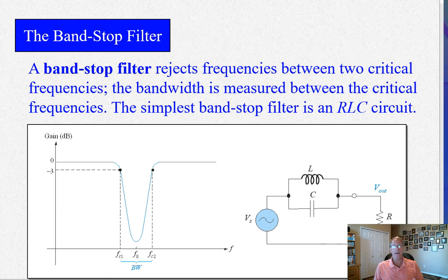And again, you can do that analysis on any circuit that has capacitors or inductors in it, any reactive circuit element. Please don't hesitate to do those boundary conditions. Find out what it's running at, what it looks like at DC. All right, at DC, the capacitor goes away, right? All the inductors, that's all that's there.